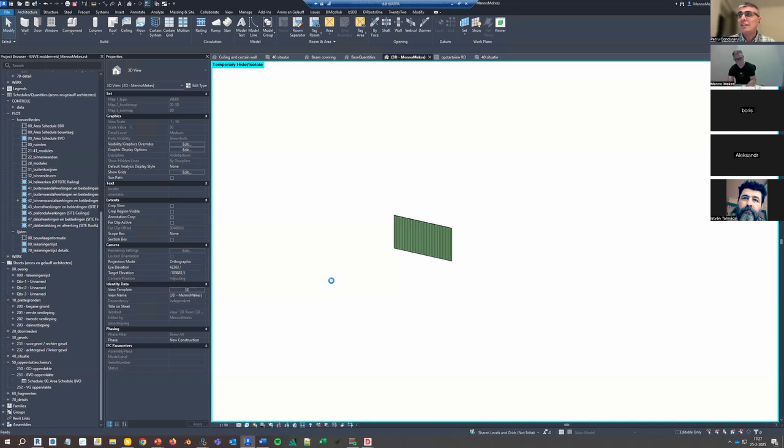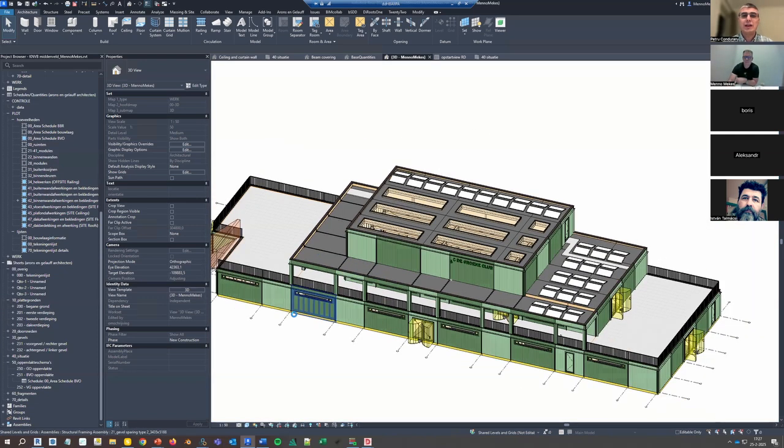I think the main reason why we get everything stuffed in a custom pset is because, first and foremost, these people who are creating these property sets don't have any clue about how the IFC schema works. Unfortunately, I'm sorry for being so blunt, but that's the truth. Because it doesn't make any sense to put something called a property, called material, in a custom property set when you have an entity called material in the IFC schema itself.